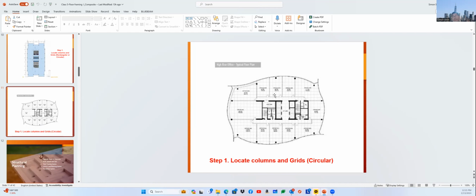Typically for offices, we prefer 40 to 45 feet. In some cases, in the old days, the Sears Tower and John Hancock might have had longer spans because at the time they were using floor trusses, not wide flange beams. But I'm talking about general current practice in high-rise buildings, where we mostly use wide flange beams, even W16, W18, W21, W24. Others might be a little deeper, but we need to factor in and size all the members to define the optimal floor-to-floor height.